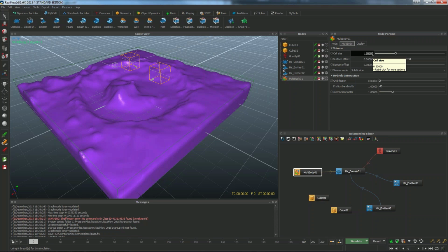So what can you do to fix that? If it happens, you can't reduce the cell size anymore, because if you reduce the cell size to a very low value, the RAM memory will collapse. So that is important. So what's the solution for that?